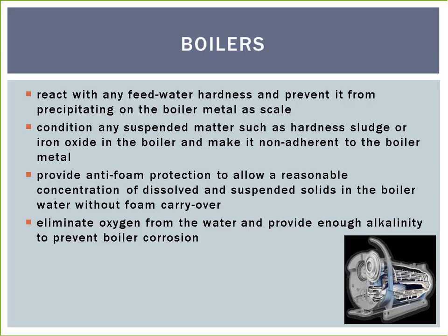phosphates and dispersants. Reacting with the alkalinity of boiler water, these products neutralize the hardness of water by forming tricalcium phosphate, an insoluble compound that can be disposed of and blown down on a continuous basis or periodically through the bottom of the boiler.